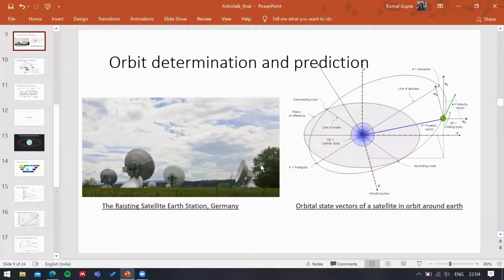But if you're in a high Earth orbit, it's more difficult to gather accurate observations. That's why, instead of using just one or two observations, there are hundreds, 200 or 300 observations used, and each observation is taken at a different time, and they all contribute to slowly decreasing the error in the position and velocity vectors that we want.